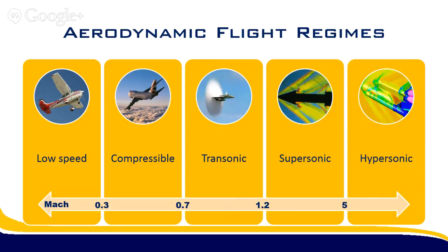For reference, a little Cessna 172 travels below Mach 0.3, so we're talking about 100 miles per hour, a couple hundred knots, whatever, or excuse me, not a couple hundred, but just about 100 knots. That's low speed. You don't have to deal with compressibility effects. This is what AE 2020 is at Georgia Tech.